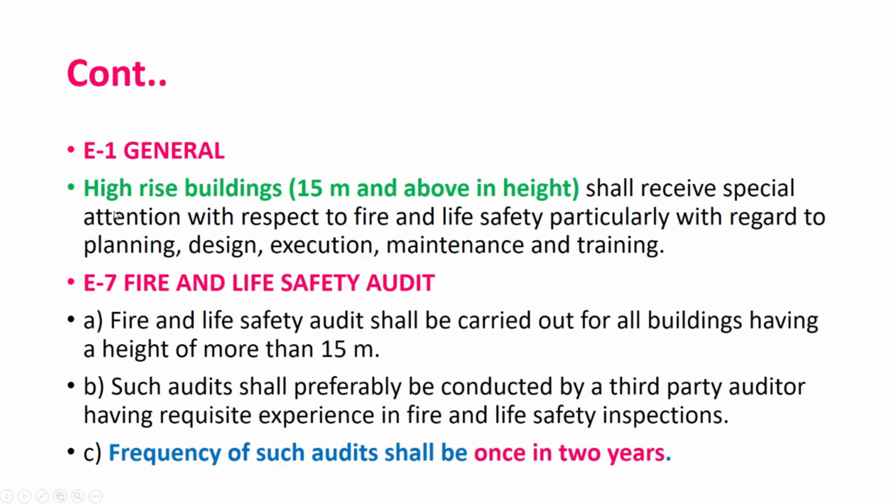Okay, but these provisions are still there. You can use pre-stressed concrete in building works, and which is the IS code associated with that? In case you want to do any type of pre-stressing activities in buildings, then you have to refer to IS 1343 2012. It may not be used at your place, but maybe in station development work, where nowadays new structures may be coming up, they may be using some pre-stressed concrete elements or structural elements. So there you might be required to see those.